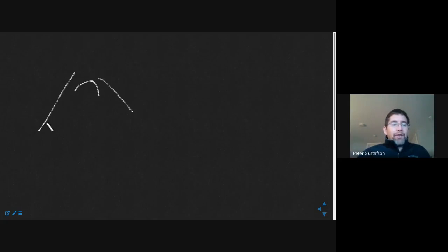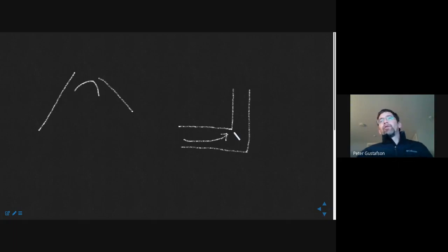In reality, if you plotted stress, once you get to this corner, and I'll draw the corner, as you're flowing around this corner with shear stress, it turns out that this corner does not idealize. In the corner, we get something that's akin to a stress concentration in some sense, but it's a change in shear flow, how it's carried.